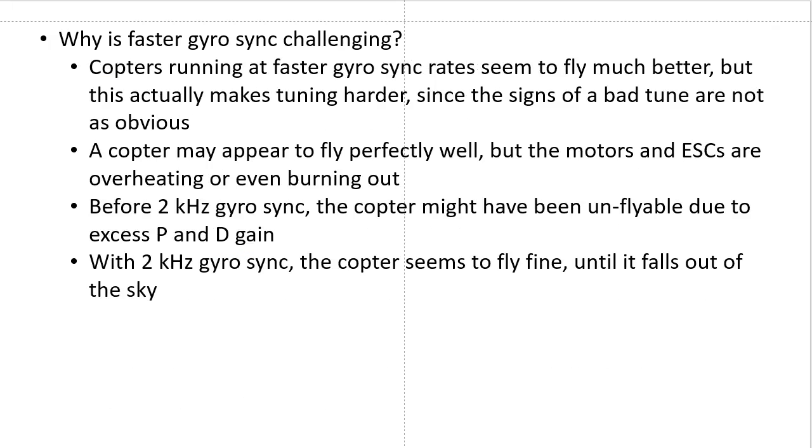There's one more reason why faster gyro sync is challenging, and that is that copters running at faster gyro sync rates seem to fly a lot better. They do. That's what we're seeing on the Betaflight thread and in the Blackbox logs that are being submitted to me. They fly a lot better, but this actually makes tuning harder because the signs of a bad tune are not as obvious. And so a copter may appear to fly perfectly well, but the motors and ESCs are overheating or even burning out because there are such huge micro oscillations.